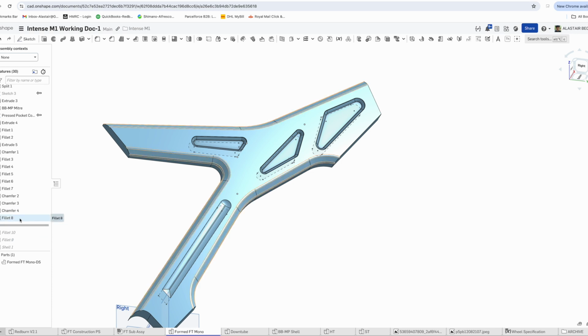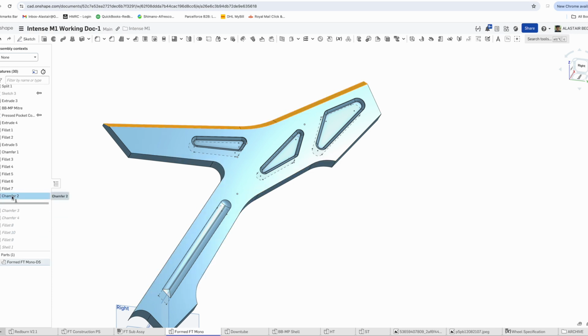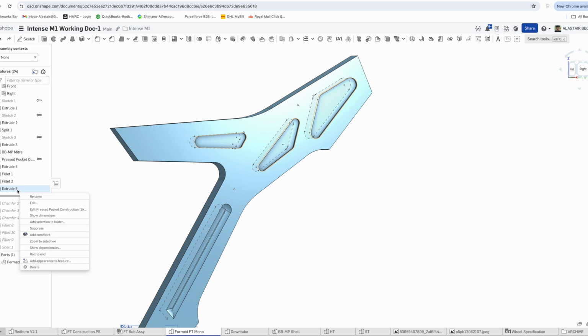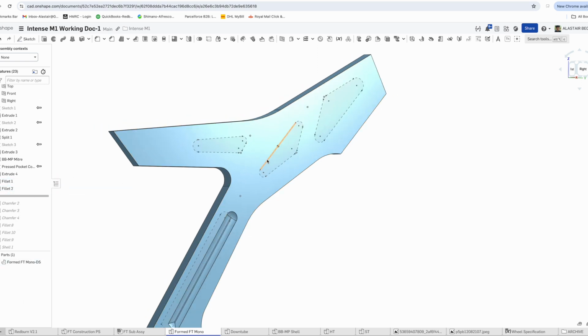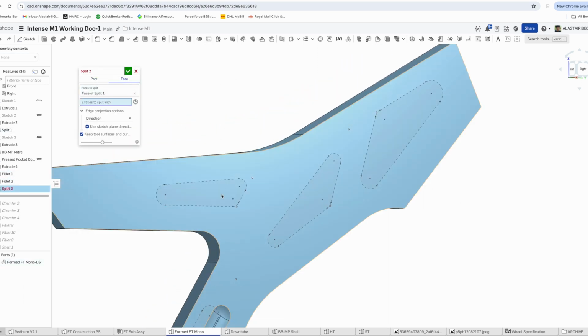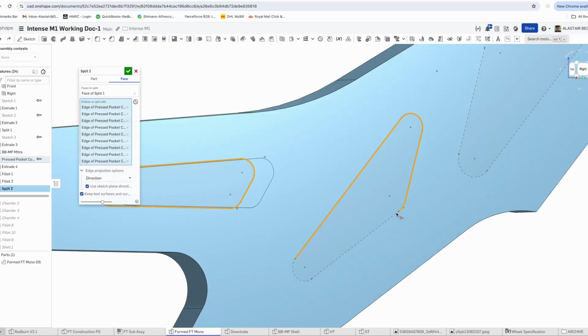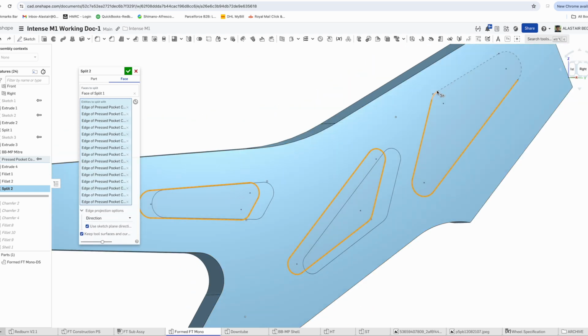So I actually redid these pockets. The first time I just extruded these and removed material from the solid. But what that did was give me a kind of weird edge when I wanted to add that chamfer, kind of 45 degrees around it. So I sacked that off, went back, and I'm just going to essentially split the face and offset those faces, and then apply that chamfer with a loft.